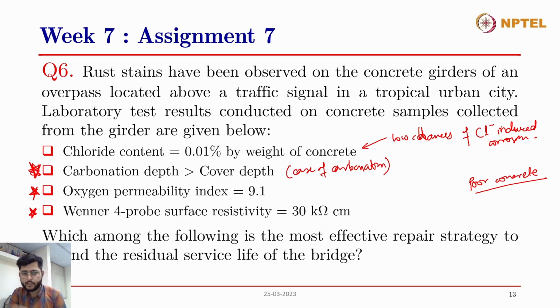Second, we found the carbonation depth is greater than the cover depth. That means that the carbonation front has passed the cover depth and is at the rebar location now. So that much depth of the concrete has already gotten carbonated, and therefore this is a case of carbonation, as Dr. Satish has rightly mentioned.